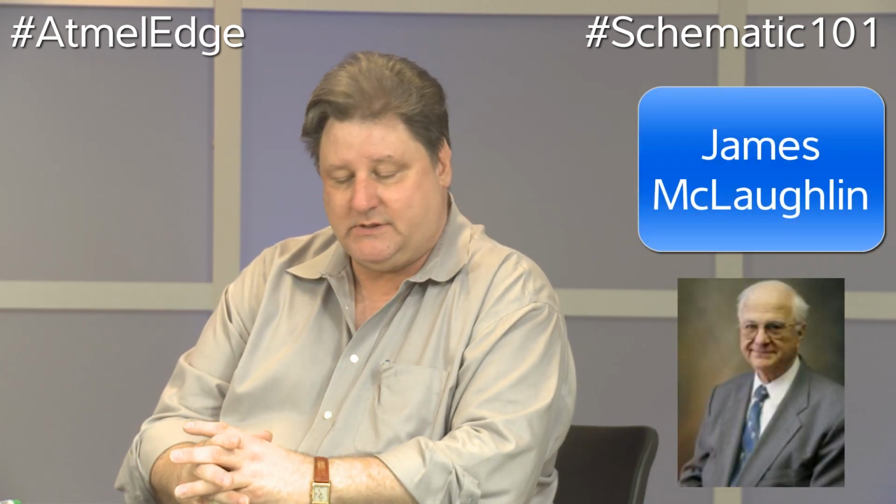My professor, James T. McLaughlin at Kettering University, now previously General Motors Institute, pointed out earth ground is a 10-foot copper-clad steel rod, and you hammer it into the dirt and you make sure there's moisture so it has conductivity. That's earth ground. The minute you hook a wire to it, well, now you've got some inductance, and 12-gauge wire all the way to get to where earth ground has to get, which is this third pin on your wall socket. Well, now it's got a little resistance as well. So earth ground means earth.